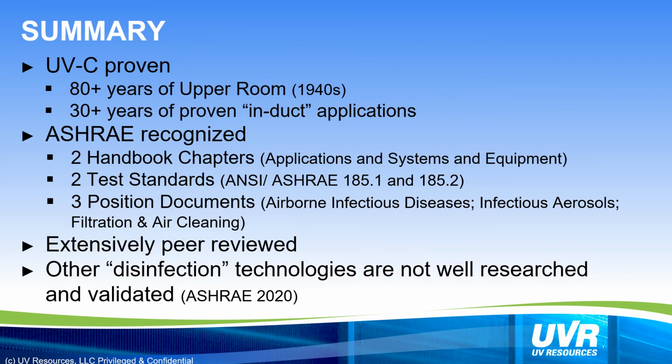So let's recap what we've learned about germicidal UVC. UVC is proven to destroy pathogens, inactivating microbes in less than a second. In general, the effectiveness of UVC air disinfection boils down to time and intensity, or said differently, how much time or duration a pathogen is exposed to the UVC energy.